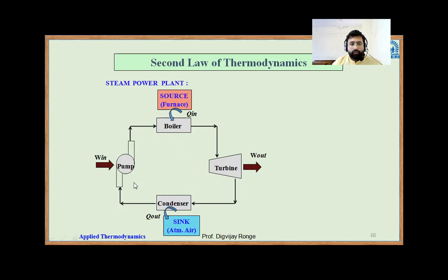Again, this water will be boiled into steam. This steam will come into condensation. It will convert to water. Water will be pumped. Again, this water will be supplied to the boiler. This way, this cycle will repeat. Obviously, there will be some loss of water during the boiling process, so some makeup water is provided in the actual power plant.